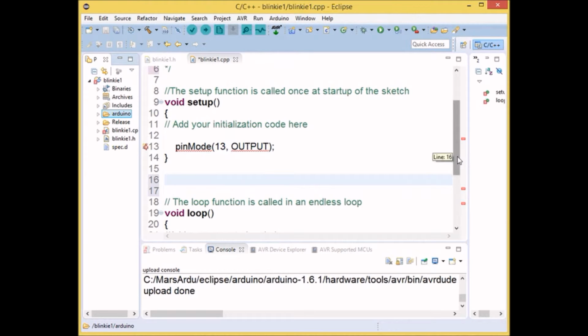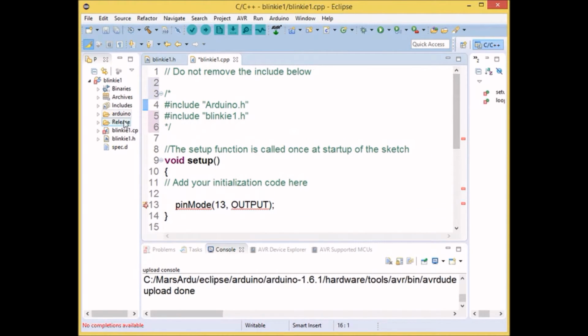because your include files are not there for it to pull from the predefined functions, okay? Arduino has predefined functions in it. Since it couldn't pull from the predefined functions, it couldn't find the Blinky.h that we have set up, which is our header file for our C++ file. It couldn't do anything, so it stopped trying.